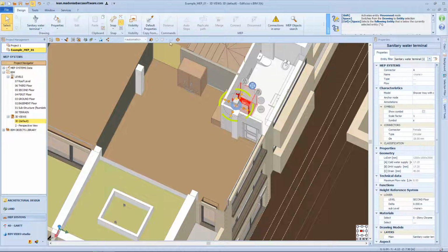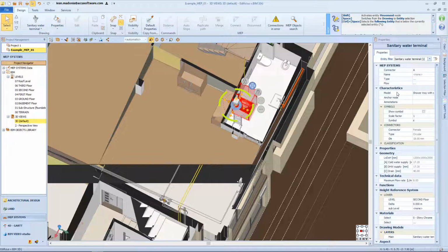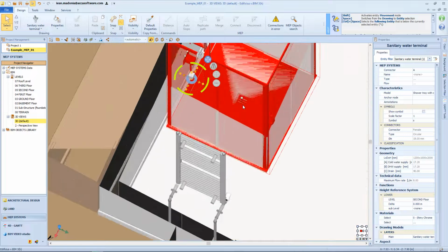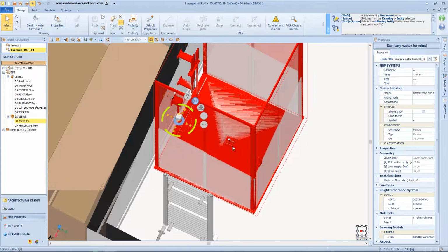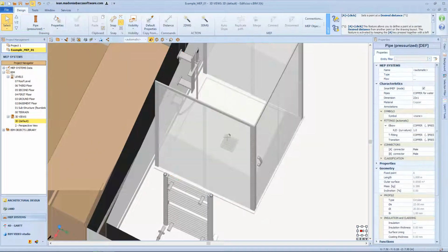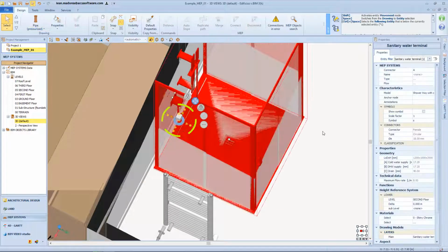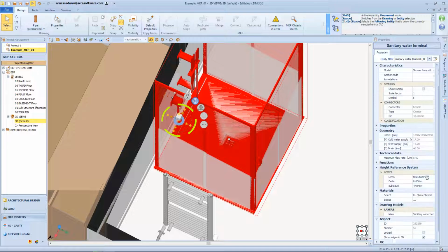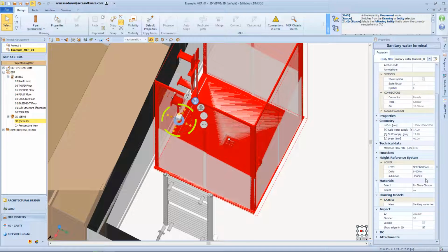Therefore, once inserted on the model, if selected, the Related Properties toolbox will show all the parameters and data that characterize it. For the fields that provide for this possibility, changes can be made to then proceed to generating any links with other entities. The MEP object obtained is therefore characterized by a graphic profile acquired from its representation in the architectural environment and modeling parameters, which now make it configurable in the MEP environment, specific to the type of entity that has been assigned to it.